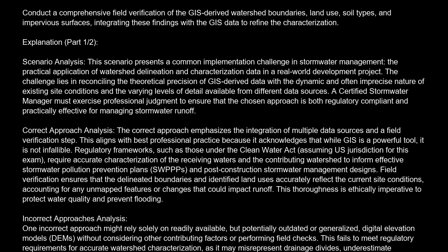Correct approach analysis. The correct approach emphasizes the integration of multiple data sources and a field verification step. This aligns with best professional practice because it acknowledges that while GIS is a powerful tool, it is not infallible. Regulatory frameworks, such as those under the Clean Water Act, assuming U.S. jurisdiction for this exam, require accurate characterization of the receiving waters and the contributing watershed to inform effective stormwater pollution prevention plans, SWPPP, and post-construction stormwater management designs.